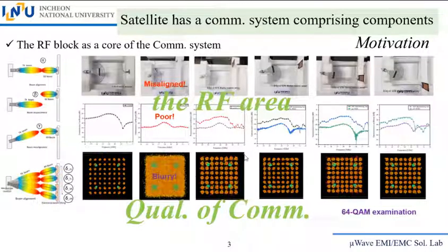And as one of my research associates has shown, the beam alignment between the transmitting antenna and the receiving antenna is important. For the sake of convenience, we changed the angle of beam from the source horn antenna mechanically, but the receiving antenna should change the beam of radiation at a certain angle electronically.